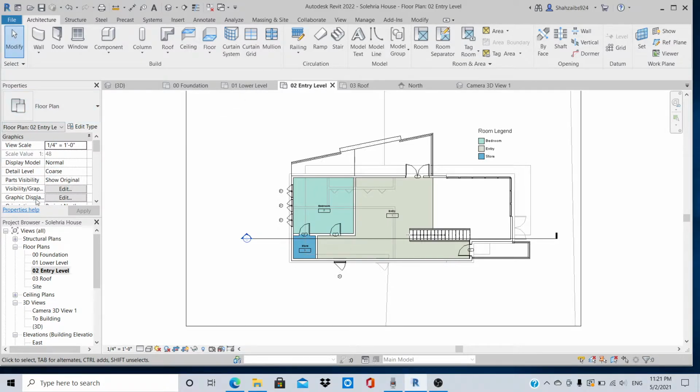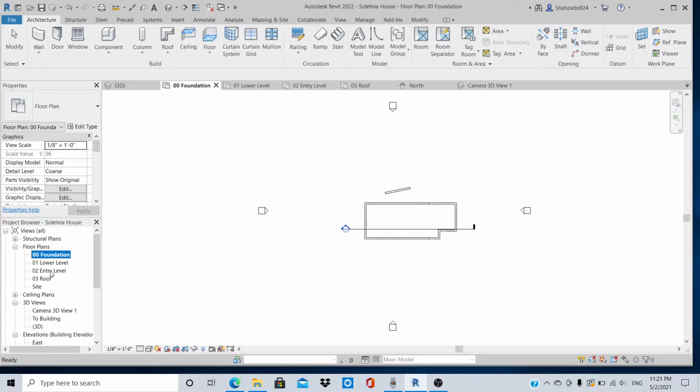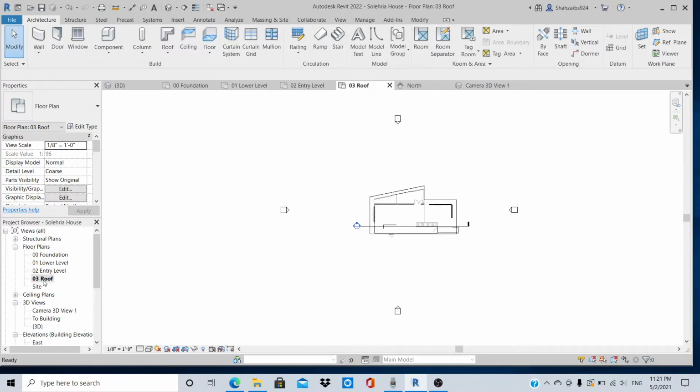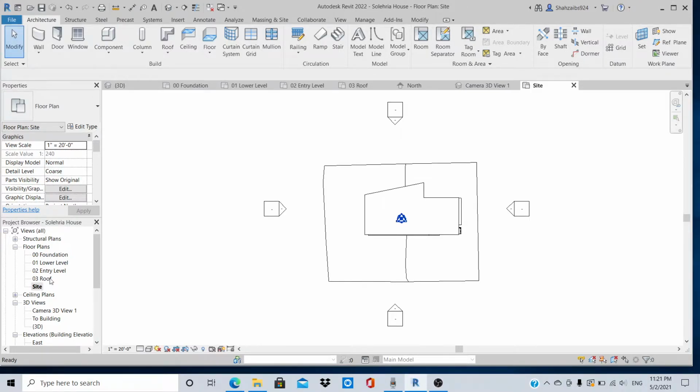And yeah, I could only contemplate the possibilities that I have with this program. More things I can do. Oh yeah, to place the top surface command, you have to go into Site. And this is what I placed. I just basically dragged out the top surface, selected it, and then increased elevations in certain areas with the top surface command. It's really a Google search away just to learn how to do that. You'll learn it in under 30 seconds.